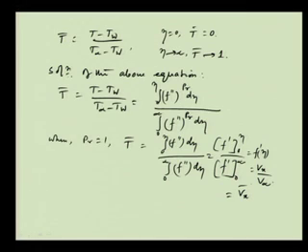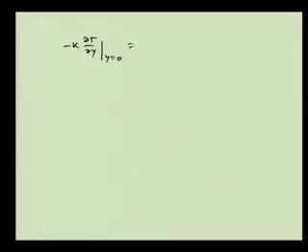Now, further we know that minus k into ∂T/∂y at y equal to 0 is nothing but the heat flux from the wall of the surface in case of boundary layer flow. From the wall of the flat plate, the heat flux takes place in case of heating a fluid. And that is equal to qw, the wall heat flux, which is a function of x only, because T is a function of x.